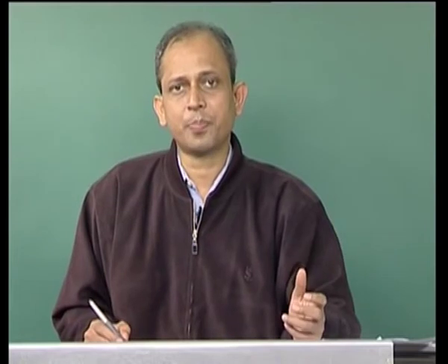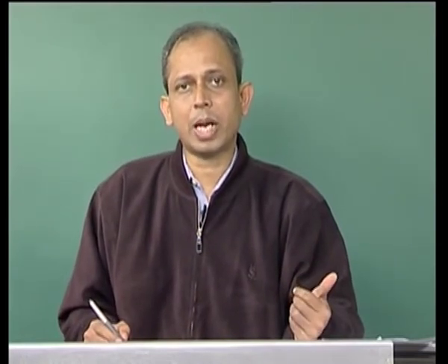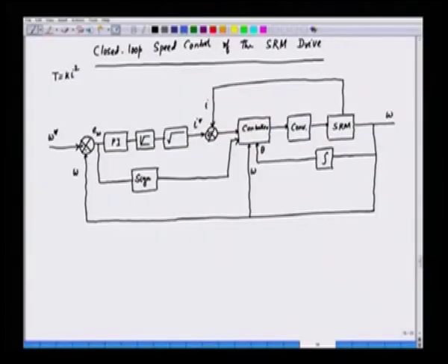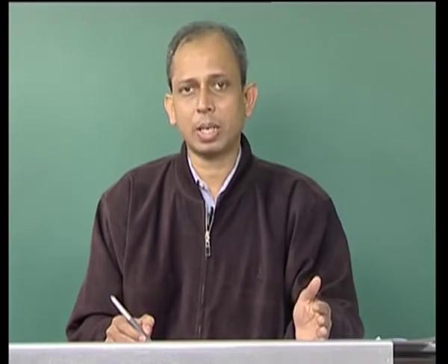a variable speed operation. Below the base speed we can have chop mode. We have the speed information which is available here, and the controller will be in the chop mode for the speed below the base speed. Above the base speed, we can go for advanced angle control or theta naught control, and above theta naught maximum we go for T omega square equal to constant till the maximum speed is reached. So this gives a complete range of speed operation from 0 to the maximum speed.